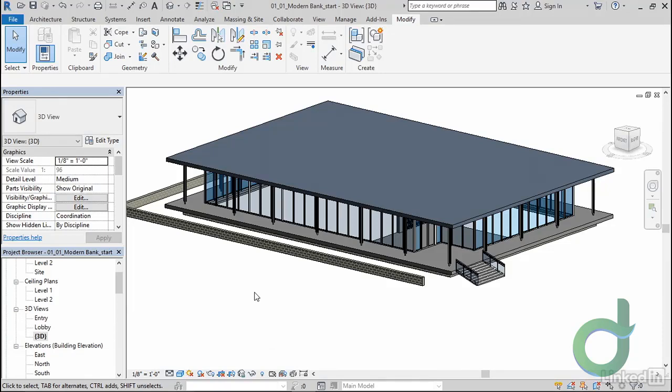When you're bringing a model over from Revit to 3ds Max, though, it's important to keep in mind some considerations that will affect the rendering later on, whatever form it takes. The first is to analyze large meshes and see where things can possibly have issues arise later when they're dealing in true light. I've got a model here I've put together, or at least part of one. It's still kind of in design in Revit, but we want to take it over to 3ds Max for more iterative design and better lighting, or perhaps go out and view it in virtual reality.